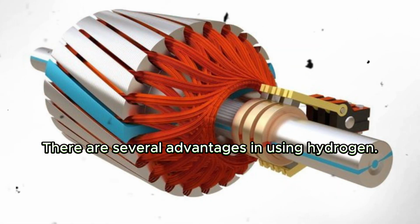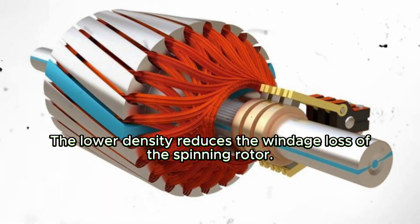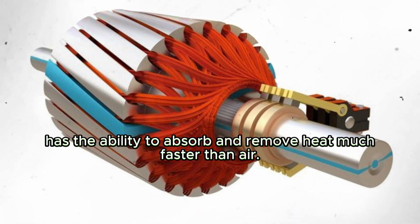There are several advantages in using hydrogen. Hydrogen is less dense than air at the same pressure. The lower density reduces the windage loss of the spinning rotor. A second advantage in operating an alternator in a hydrogen atmosphere is that hydrogen has the ability to absorb and remove heat much faster than air.